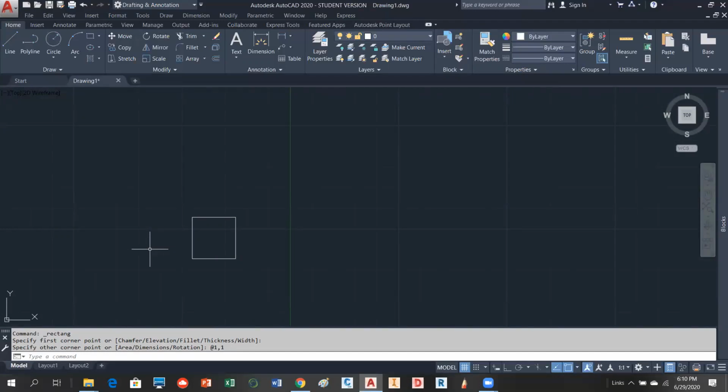So we're going to go into the array command. And the reason I wanted to know what this distance was, because when you do the array, if I'm going to have another square over here, I have to know what the distance is across this face, because I have to add that to whatever distance I want it to be offset. So when it talks about the array distance, it's always this distance plus whatever you want the offset to be. Same thing works this way. If I'm going to pop a square up here, it's going to be that distance plus whatever the offset distance is, okay?